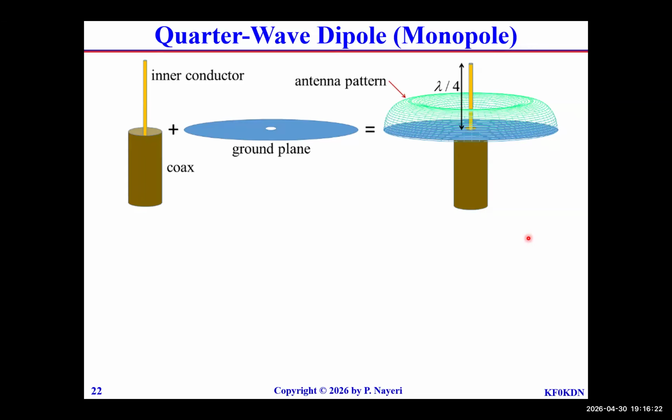Typically, this is a decent impedance. When you cut the antenna in half, in this case, λ/4, this impedance almost gets cut in half. As you keep reducing the size of the antenna, its input impedance becomes smaller and smaller. It may even go below 1 ohm.